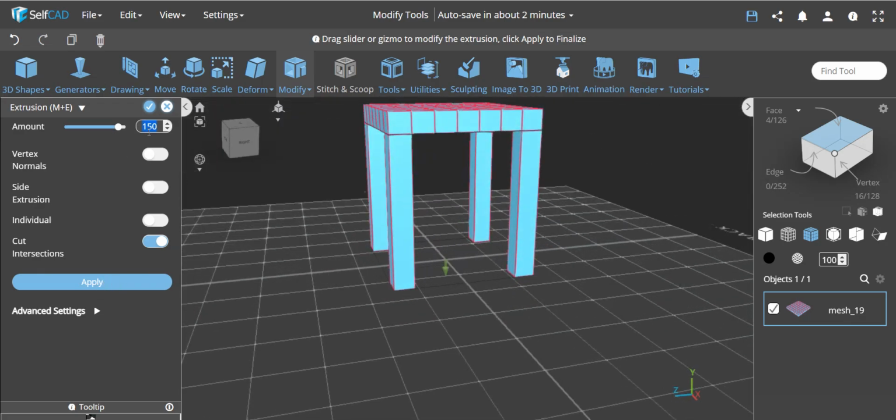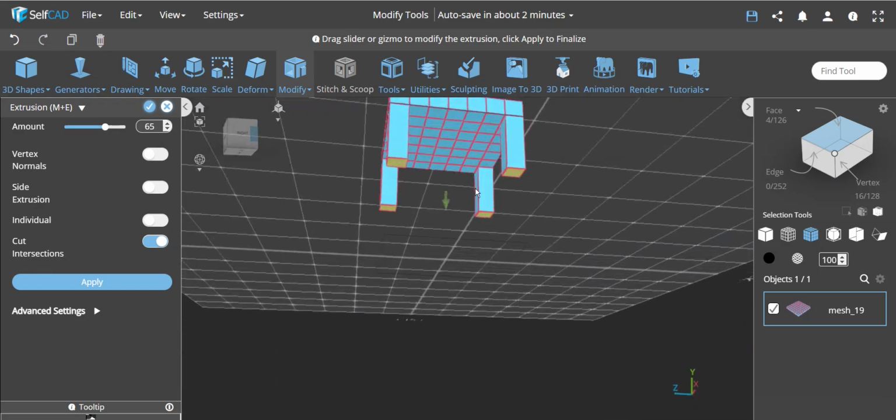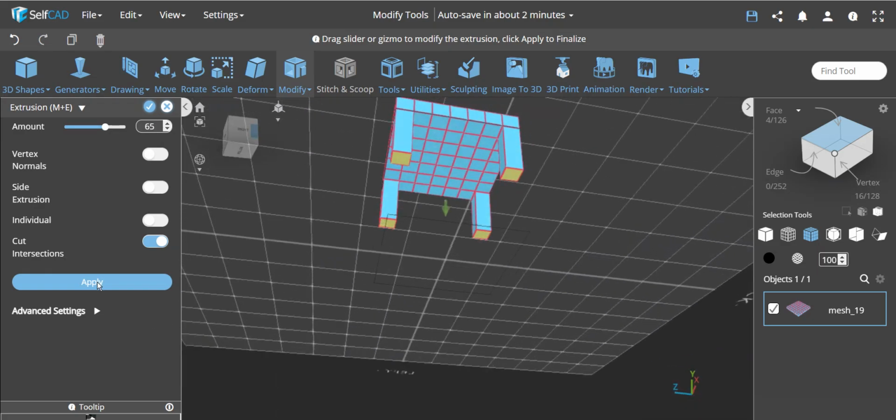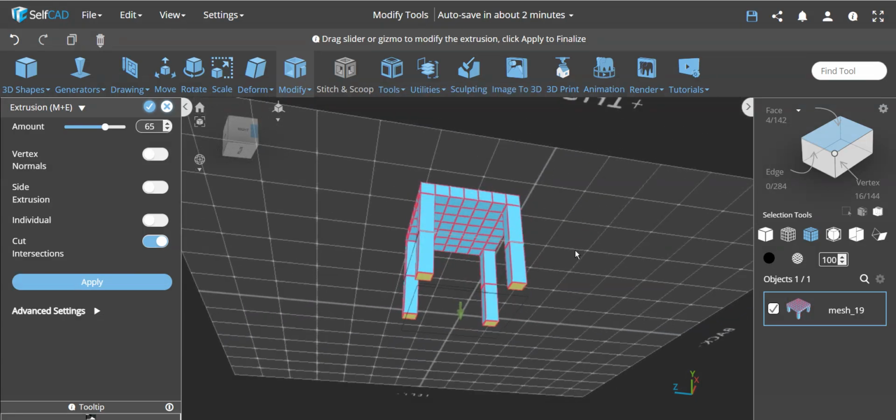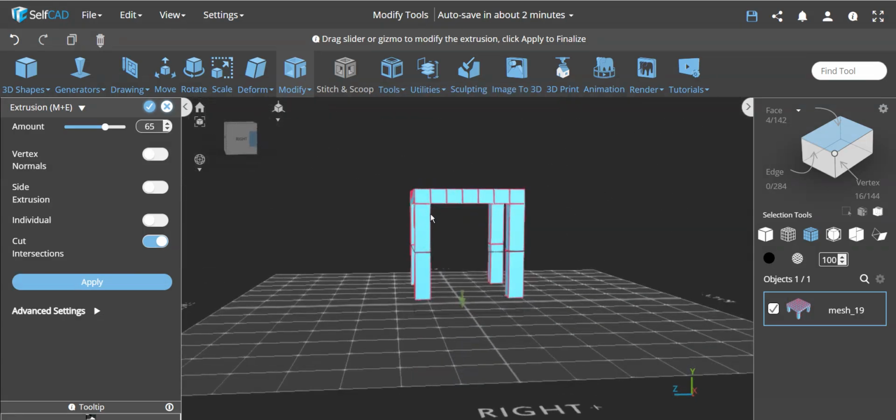So in this case, I'm going to use the first segment as 65, and then in order to make a segment I have to click apply. Now if you think about what happens when I click apply, it confirms this is already done so that I can change now a different value. If I exit out, I cancel, everything will be cancelled. But if I continue going and I confirm it, this will be confirmed. So now the second value, I'll enter 20 over here and I click apply.